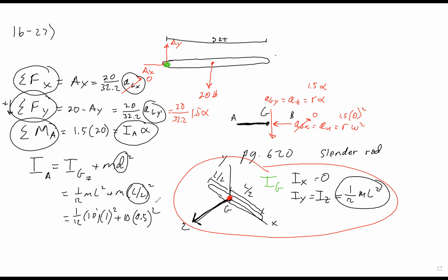And then they're squaring. That's how we calculate the rotational inertia of an object rotating about a point that isn't at the center of gravity. We take the rotational inertia given to us in the table at the center of gravity, and we add this shifting term for the distance that we want to shift. We have to take into consideration the mass of the object. With that, let's erase these and apply this concept to the problem we are actually doing.